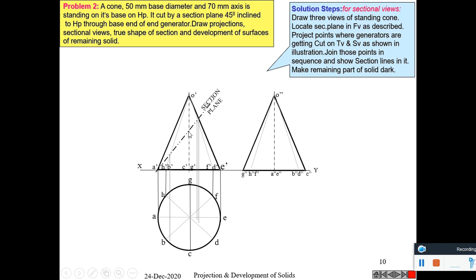To project a point from the center line, it should be projected first towards the outer generator or side, O dash A dash. Then it is projected downwards to OA. From there arcs are drawn to either side, to the C and G direction. And mark those points. Similarly, it is projected towards the right as well, and those points are joined using a smooth curve.